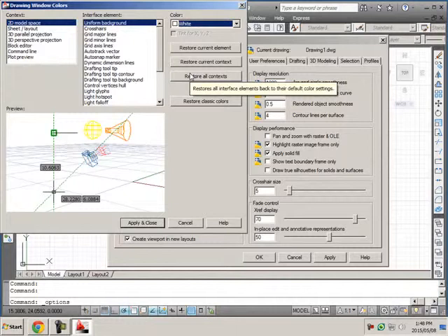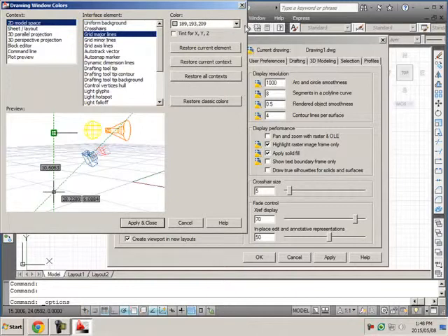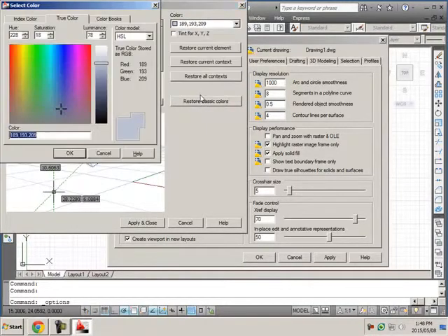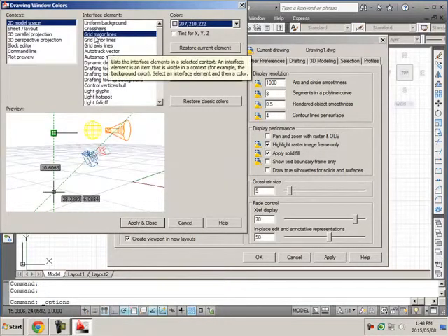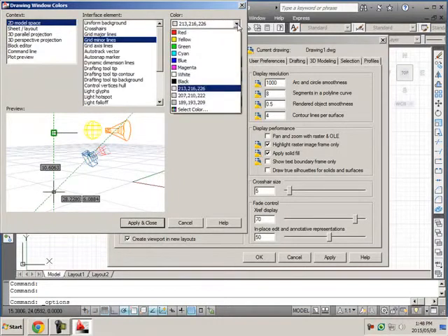You'll find that your grid is very dark, and so I've come in here and I've clicked here and gone into Select Color, and then it's by default about here, and I just made it lighter and said OK. So I changed my major grid lines and I changed my minor grid lines by doing the same steps.